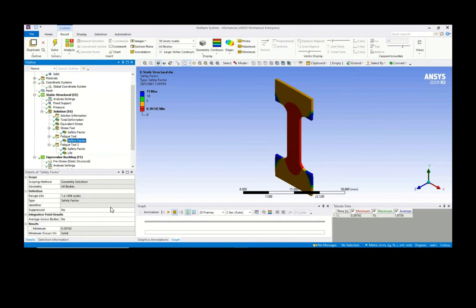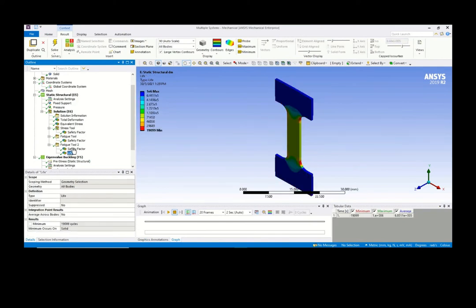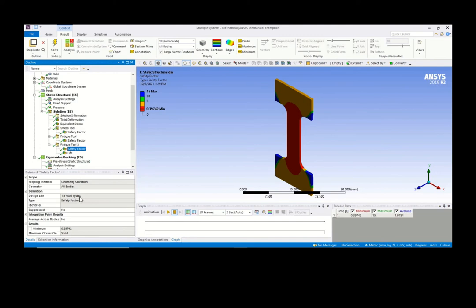Then here, design life is 1E6. You have to set this 1E6. Just now I forgot to set it here, so I put 1E9, so it can be set previously. So 1E6, right? So we would actually say that fatigue is likely to happen. It's below 1,